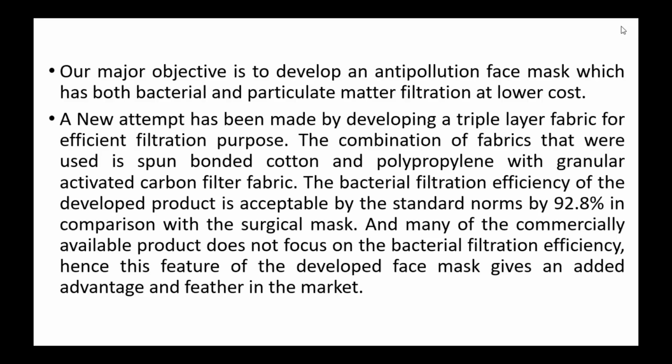The bacterial filtration efficiency of the developed product that I achieved is acceptable by the standard norms, at 92.8%. I have achieved filtration efficiency which is on par with the surgical face mask. Many commercially available products do not focus on bacterial filtration efficiency, especially with respect to particulate matter.